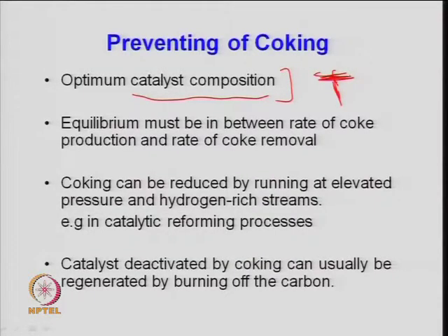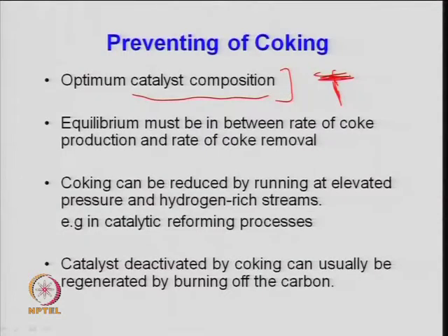Pressure again has some effect, so you need to find out whether high pressure or low pressure. Generally, high pressure will avoid the coke formation, but higher hydrocarbon partial pressure will increase the coke formation. The concentration of coke precursor will increase the coke formation. So, equilibrium must be maintained between the rate of coke production and the rate of coke removal.